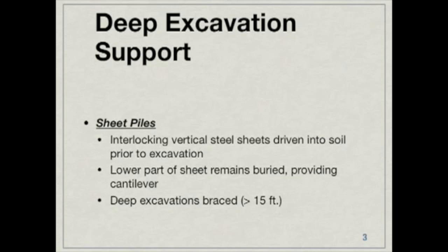Typically, a cohesive soil that has a shallow vertical cut, we're talking about 5 feet or so in depth, you may not need any kind of a support system. However, typically you're going to be going a lot deeper than that, and deeper vertical cuts must be provided with a support system. A few of these systems are listed here, and I'd like to discuss them in detail.